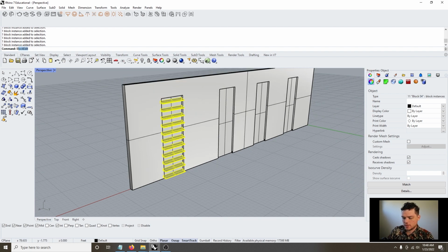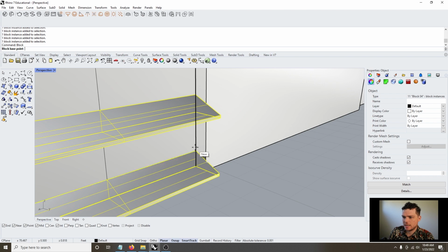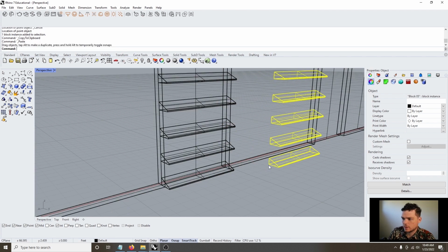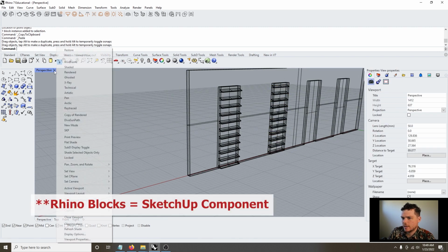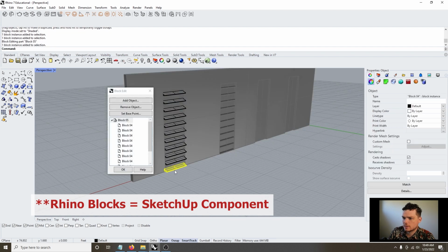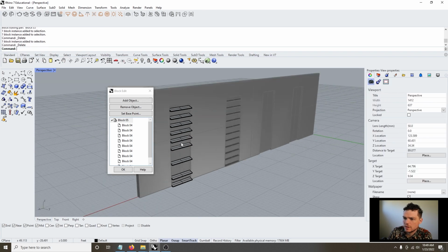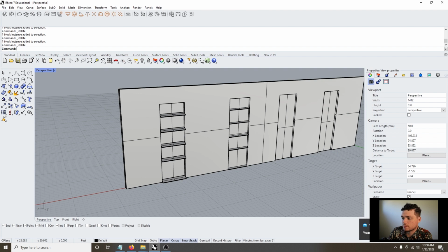The first one is you could create a block within a block, and that effectively does the exact same thing. So I could create a block, what we're calling a block within a block. And that works the same as a group. So if I select this, and let's say I wanted to thin this out, now it's going to change every single one of those blocks.